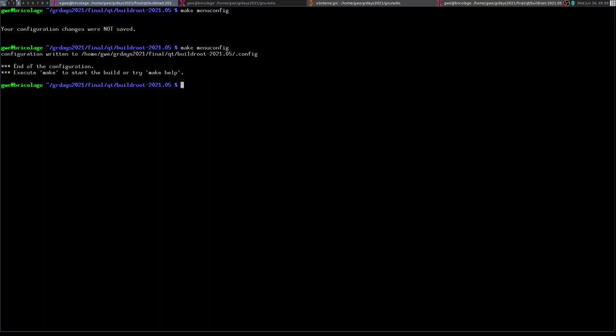Again, as mentioned earlier, the GNU Radio configuration has been updated, so it's required to use reconfigure to explicitly force Buildroot to apply all steps to this package, and finally make to build and to generate a new image.